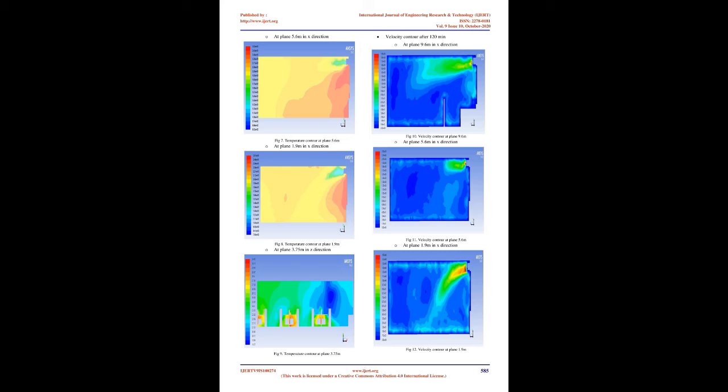Data obtained from the experiment is plotted for CO2 concentration, temperature, and humidity against time as given in Fig 2, Fig 3 and Fig 4 respectively. From Fig 2 it can be seen that at the start itself CO2 concentration is 1000 ppm. According to ASHRAE Standard 62.1, 1000 ppm is the permissible limit set, and it can be seen that at the start itself it is exceeding the limit. It is due to the fact that the room is closed as no ventilation is provided in it. From Fig 2 it can be seen that down the line it will eventually cross the 5000 ppm mark, which is the hazardous limit set by ASHRAE.